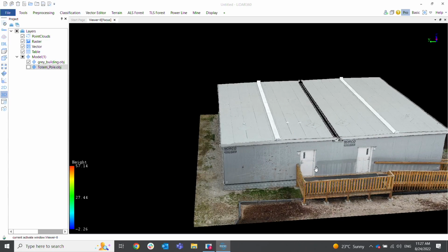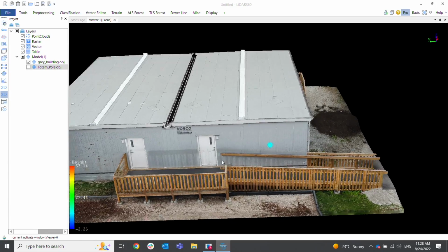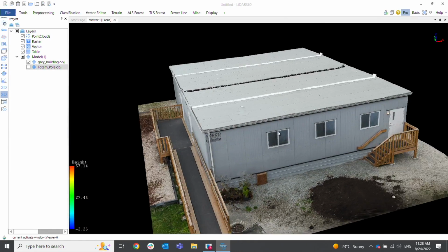Amazing, yeah. So with a model like this, if we were to use terrestrial scanning, we could actually take dimensions from this and then use our photogrammetry model to apply the realistic look to it. Exactly. Well, if your industry is film, TV, and video games, that fidelity may not necessarily be needed. It would probably speed up some of the workflow and the timeline of processing the data. But if you're trying to get into more engineering and surveying with this type of application, combining with a laser scanner is key.